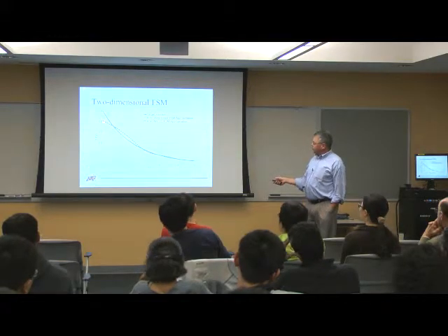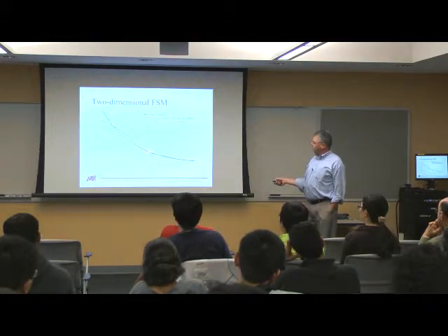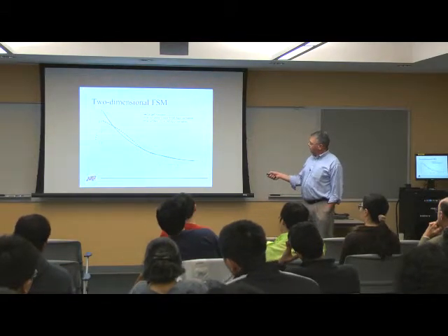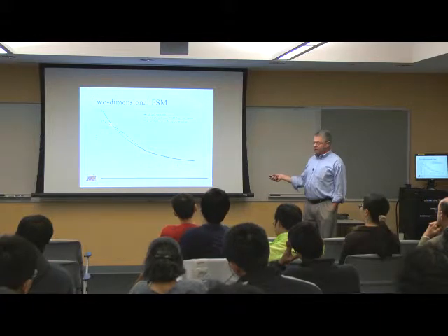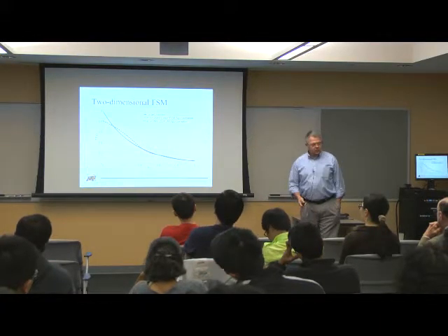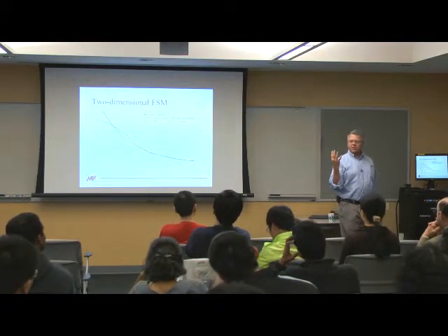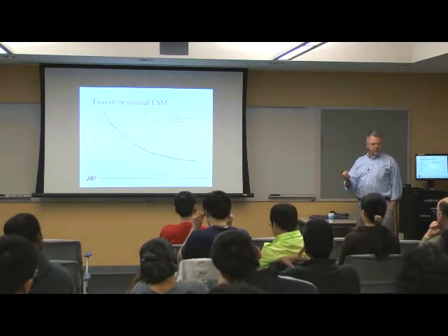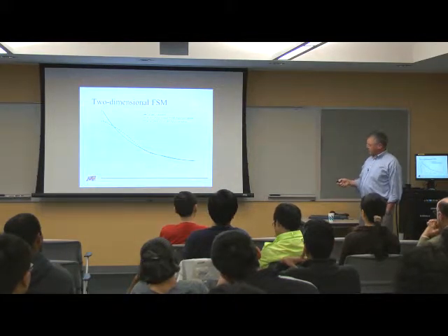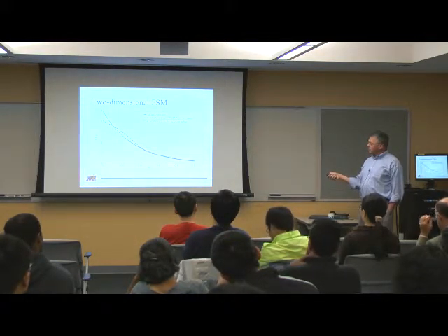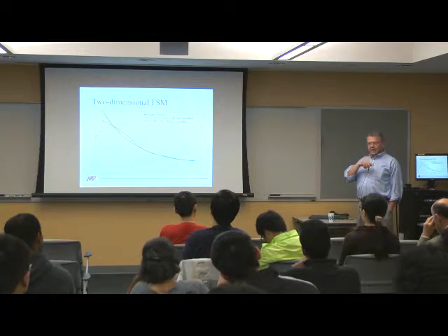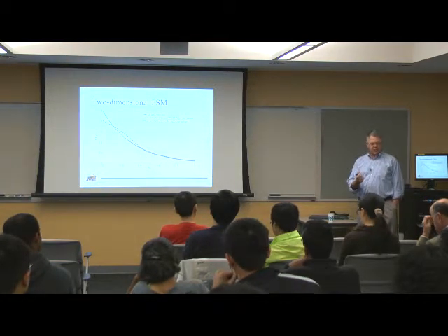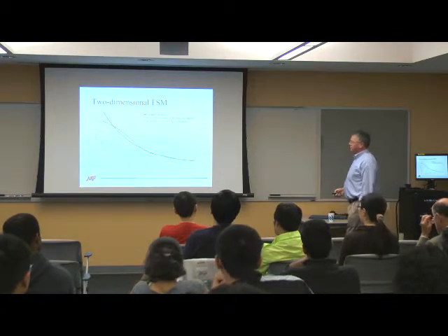Here's that function that I was trying to approximate with a 32-state linear machine, and I couldn't get very close. Here, with 4 states in the 2-dimensional version, I'm right on top of it. So think about that. A 4-state state machine is 2 flip-flops. So with 2 flip-flops and a few other logic gates, I can implement this kind of function almost perfectly. And I can do lots and lots of functions very, very close with just a couple of states, a very small state machine.